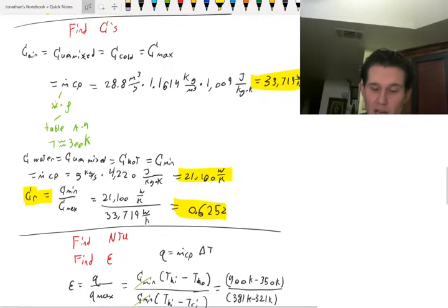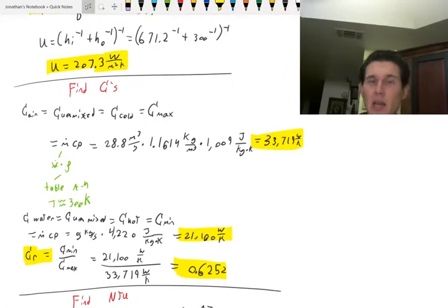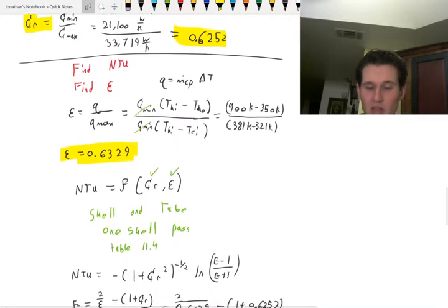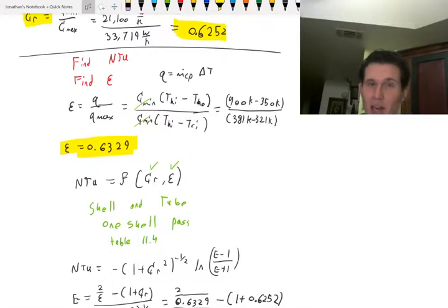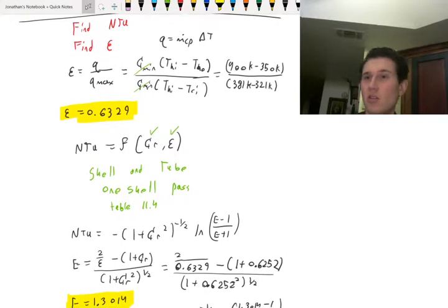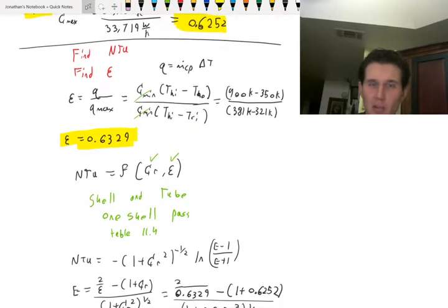And remember, for that error that we calculated, we had to get the density to multiply by the volumetric flow rate at the temperature at the inlet where we measured, where we have the known value of that volumetric flow rate. So remember, get the value for density at the point you have the speed or the volumetric flow rate. And to use, it's another form of fin equation. It's like a shape factor. It's essentially modeling more complex systems, just having an approximation, a factor. Somebody else set up some experiments or derived something for us to make our life easy.